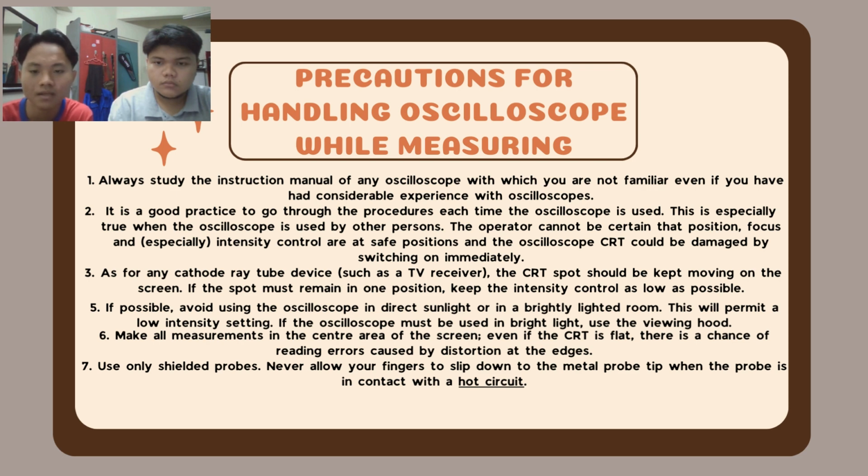Number six, use only shielded probes. Never allow your finger to slip down the metal probe tip when the probe is in contact with a hot circuit.